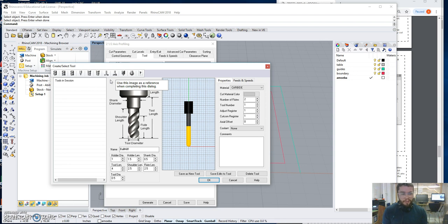The difference between a flat and a round tool is that round tools are generally better at doing three-dimensional contouring surfaces, topography. Flat tools are better at just cutting things out and also cutting sharp-edged details into things when you need them. For this and for most plywood cutting operations at a smaller scale, we're going to use a 1/4-inch flat bit. There are different types of 1/4-inch flat bits, but that doesn't matter after this point in RhinoCam.